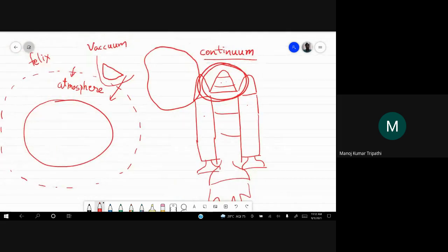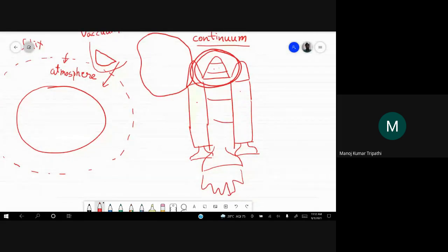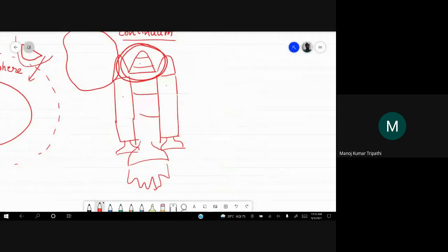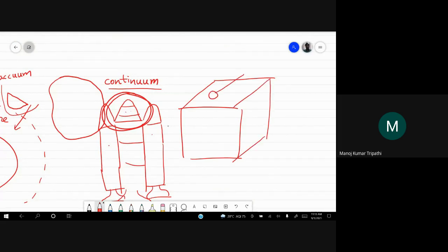All right. So can you apply the equations of fluid mechanics that we'll be studying in this course, assuming that the material is continuous? Can you apply it here, near the boundary between the vacuum and the atmosphere, or in the outer atmosphere? Because the mean free path is so much that for a 1 cubic meter volume, you have only a few molecules of air.